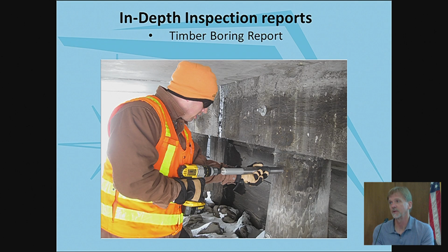You can either have a vertical scale that shows where you're at in the timber member, or a stylus that draws on a piece of graph paper. When it's a flat line, that means it's full of rot, or you've hit a split or something like that. It's pretty low tech, pretty expensive, and made in Germany, but it's really helped us to determine whether that particular member has to be replaced.